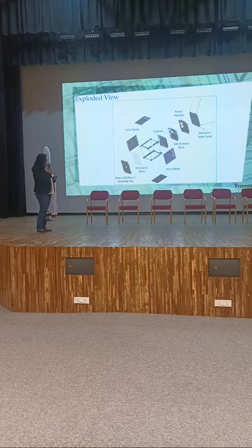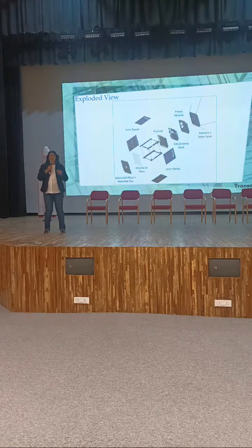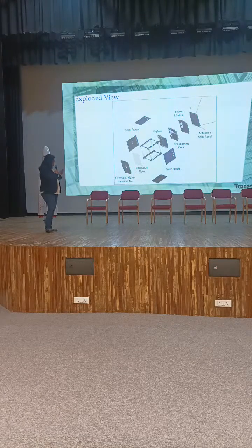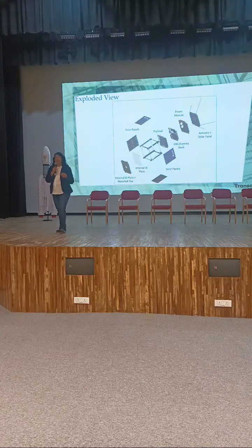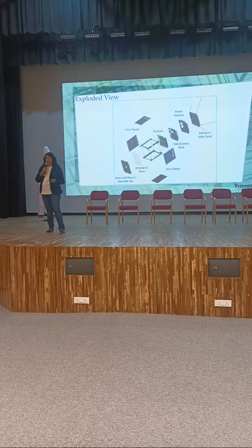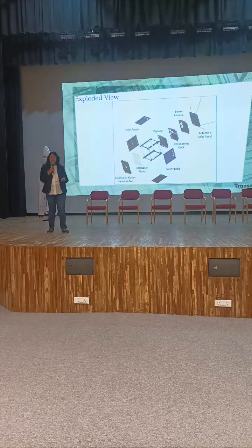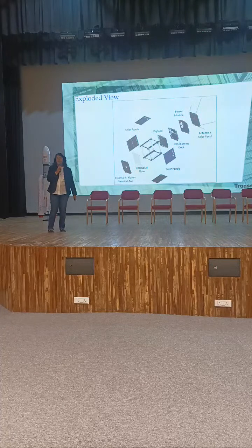So for example, if you have an imaging payload, where you have hyperspectral imaging or SAR imaging, the amount of image data is very huge, because each image is made up of a very high number of pixels. Then the data required to send one image to the ground station is very high. It is not possible in the UHF or VHF kind of frequency range. Then you will have to design for a higher frequency range, like S band or X band. So that's how the selection of your payload also helps in determining your communication system.